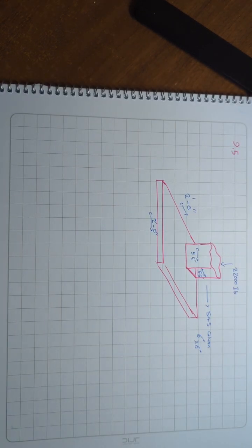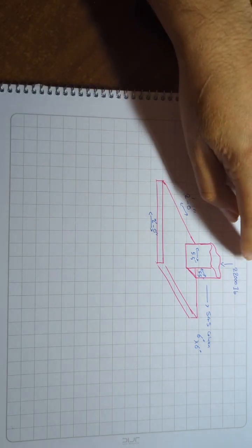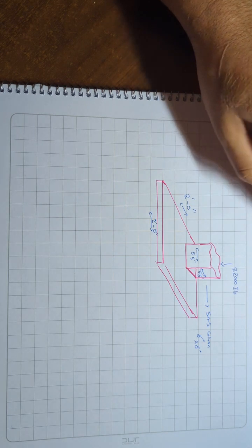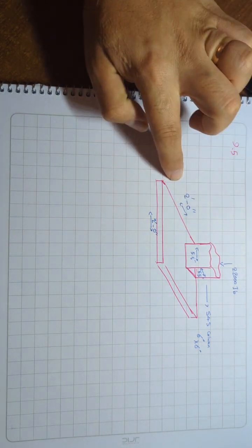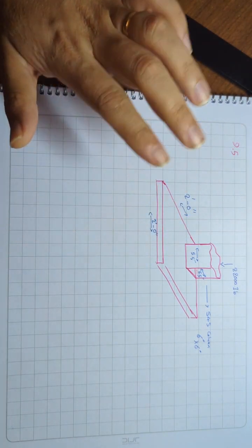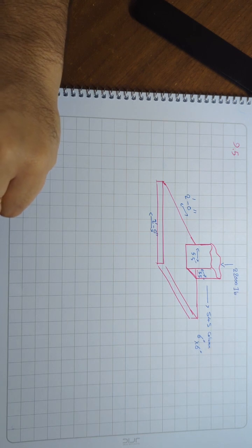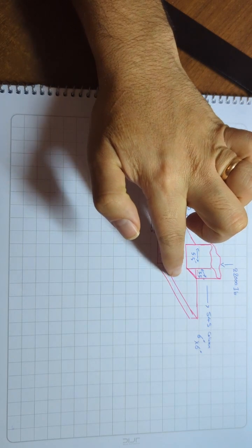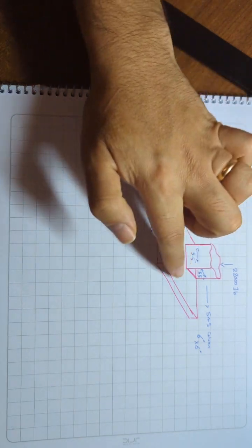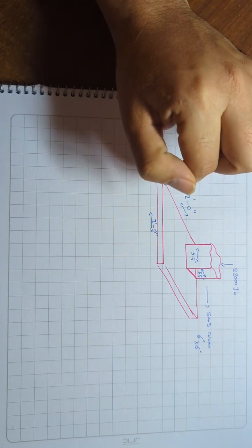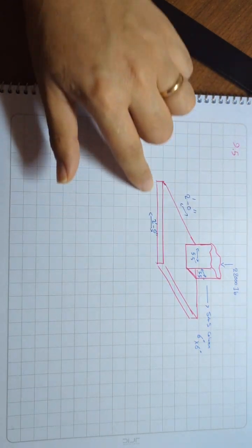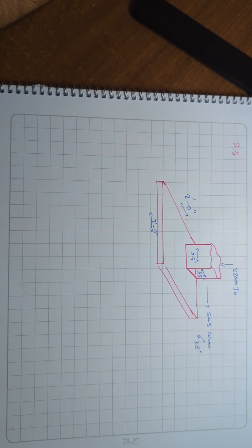Okay guys, example 9.5. An S4S timber column, nominal 6 by 6 inches, is subject to a compressive load of 22,000 pounds as shown in this figure. The column is supported by a 2 feet by 2 feet square concrete footing that is in turn supporting the soil. A, compute the bearing stress on the contact surface between the column and the footing. And B, the bearing stress based on the footing and the soil. The example wants us to neglect the weight of the footing and the column. So it's pretty simple, right?